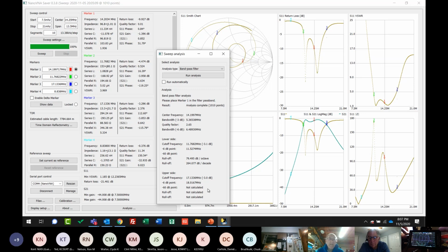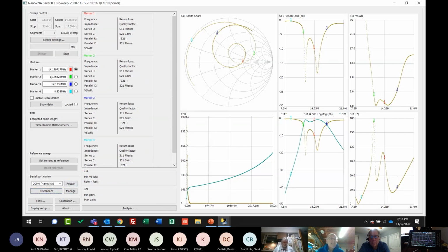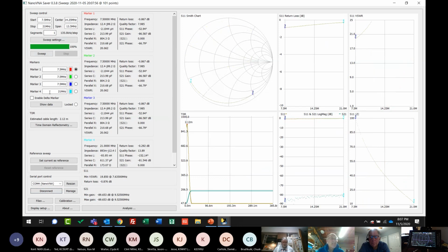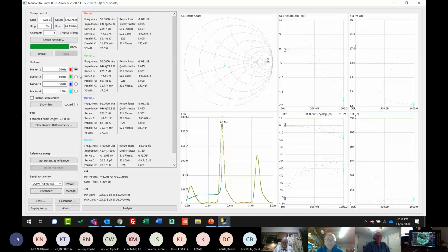serve us pretty well. So what I've got here is that's connected up. There's a small jumper. You can't quite see off camera here. And we're going to go ahead and I'm going to disconnect, and then I'm going to reconnect. And what that'll do is that will reload my scan. Oh, no, it won't, because I haven't done that yet. One second here. So I'm going to disconnect. We're going to recall. We saved our parameters in 1. We're going to reconnect here, and that will put us in, again, our 50 kilohertz to 1 gigahertz sweep.